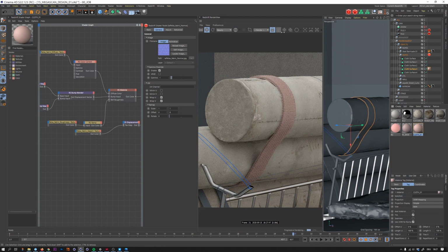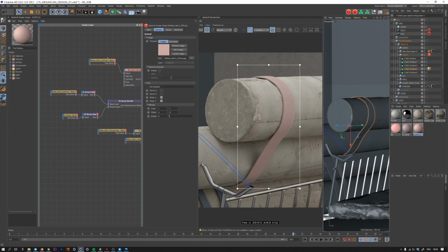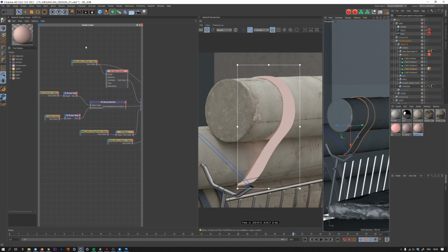And let's see how our material looks. Therefore, I will just give myself a preview on there. And I think this looks already quite nice. But the displacement is obviously way too much. It's getting somewhere. 0.3, I guess, might be the correct thing. Yeah, I would say this is about it. Then to the texture. I'm just previewing this material itself, and I see how the stretching is. And I think that's already quite good.